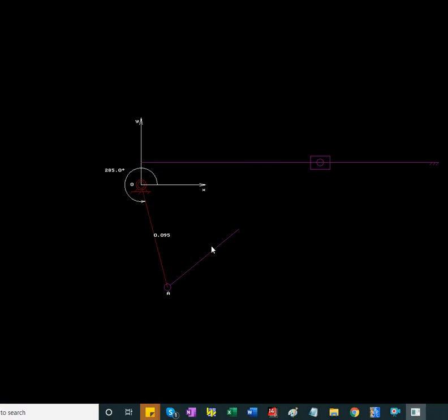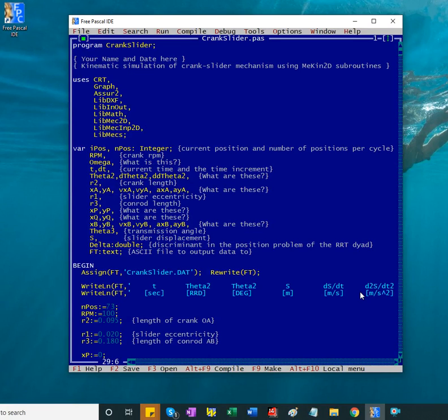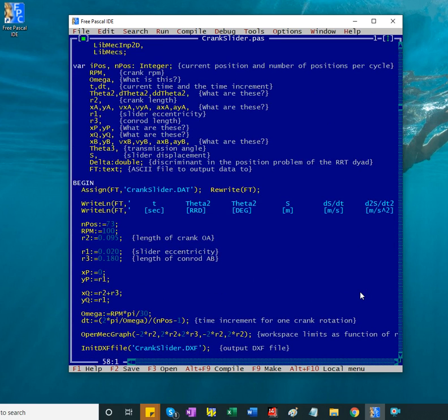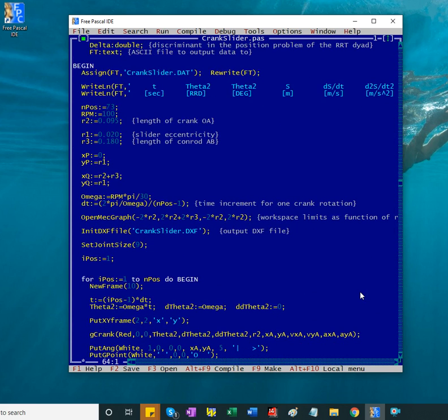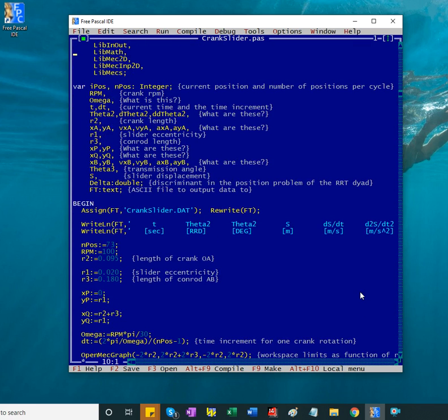If the direction would be at some angle, then I'm going to introduce you to a function, or a subroutine, that is not used in this program, but those interested in practicing with the collection of subroutines that I'm providing you with may want to experiment with. Okay, so in addition to delta, if you remember, when solving the kinematics of the slider crank, there is a quadratic that you have to solve, and the delta of the quadratic has some relevance because its values change, and it's getting closer to zero when the mechanism is in its limit positions.